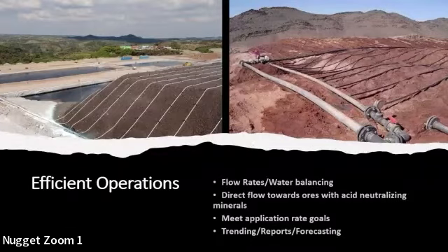So this is just an example of the cell. What it looks like on the left is a 6-inch diameter column that's actually undergoing unsaturated hydraulic tests. There are emitters, drippers here on the surface, dripping onto the surface at a particular rate, and we're monitoring the solution content and the matrix potential within the column. On the right is a 12-inch diameter flex wall column that's undergoing saturated hydraulic conductivity measurement. You can see it's a fairly large column, and all the test work that I'm presenting here was done in a 12-inch diameter column.